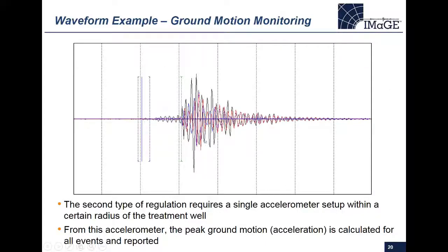This one hasn't been rotated to the PNS wave component, so the colors don't necessarily match that. But you can see the onset of the first arrival here is the P wave that's being picked by the blue line. Then it gets a little bit stronger, and then the shear wave really arrives here where the green is onset. So from this, the main deliverable we'll get is being able to calculate the peak ground motion or the peak acceleration value. And that will be independent of any picks. It'll just be the trigger, and the peak acceleration value is the value.